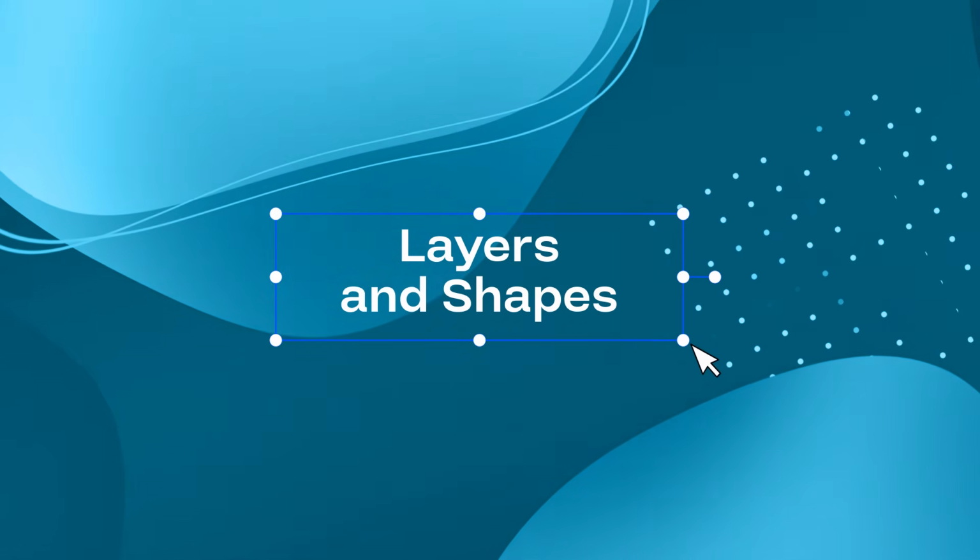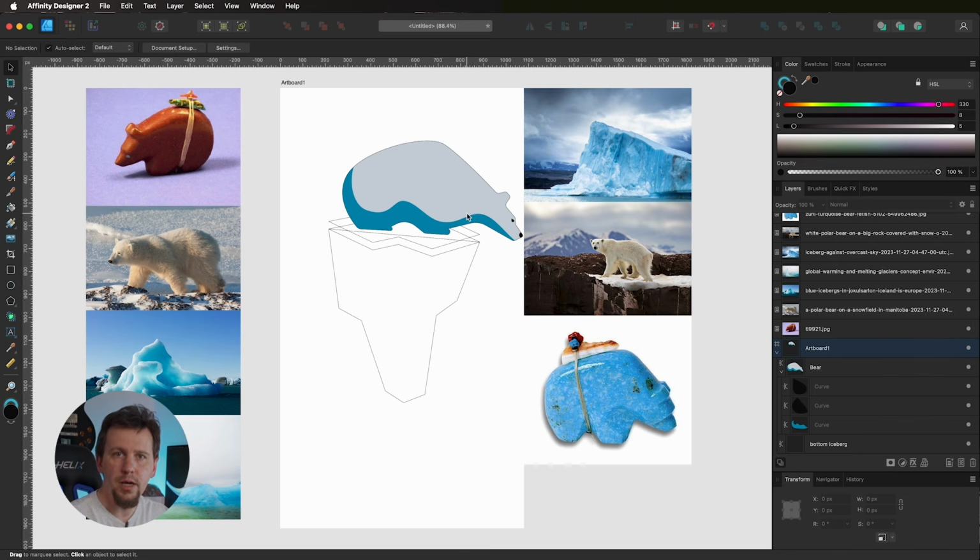Next, let's have a look at the vector paintbrush. The vector paintbrush combines raster and vector elements. It can paint raster strokes and texture along a vector line. Exporting these may not be supported depending on the format you choose, so you might want to experiment before doing a whole project with it. But we'll go ahead and activate the paintbrush on our toolbar, and we're going to add a little bit of highlights to the bear. We'll activate the paintbrush here.